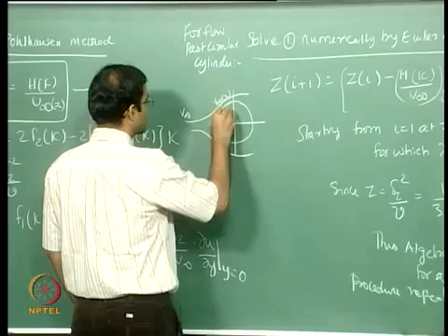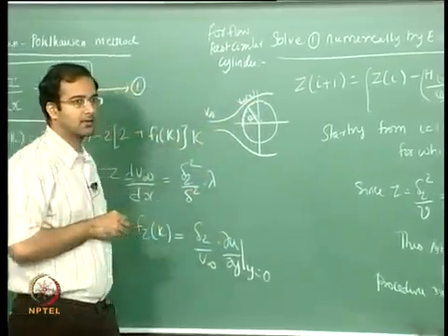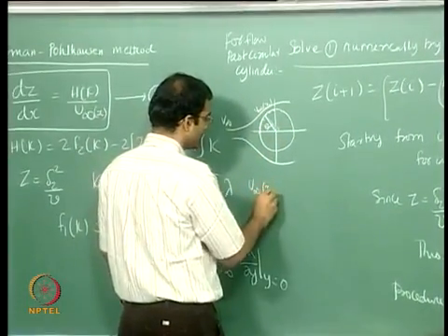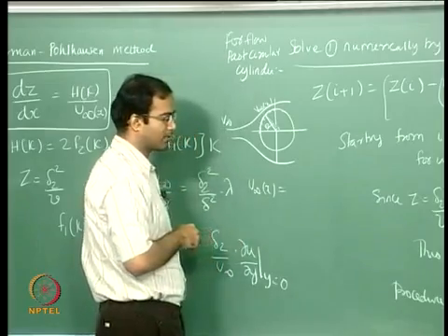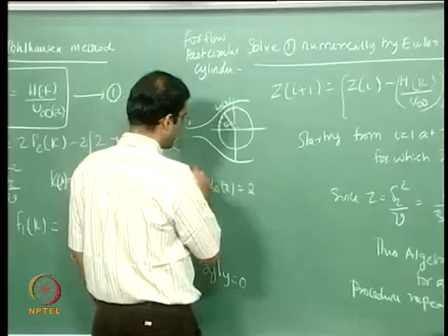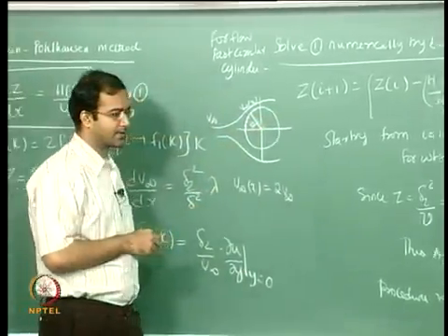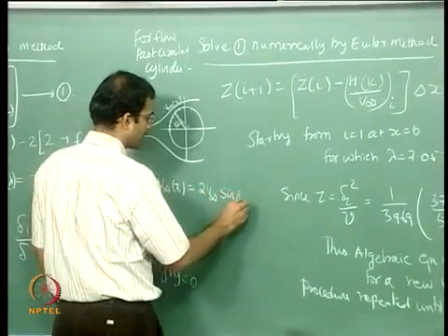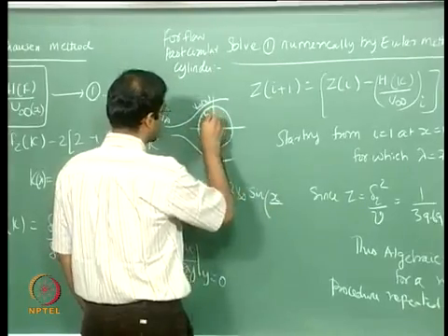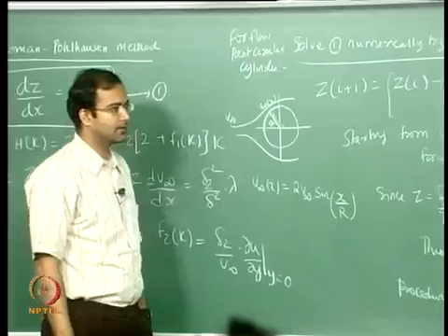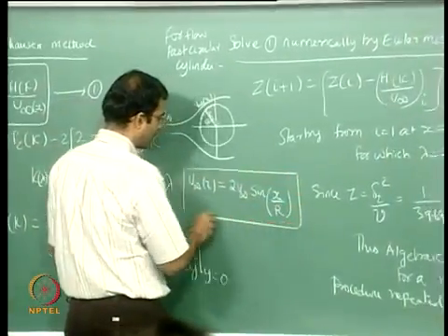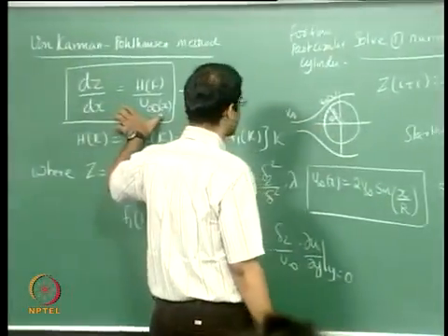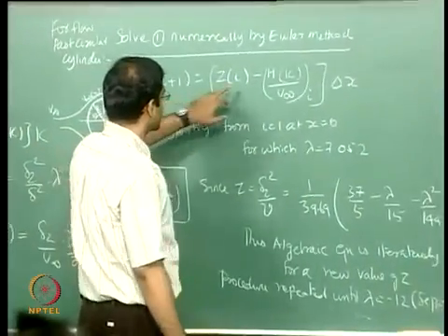We can discretize this particular ordinary differential equation for many points starting from the stagnation point. Suppose we want to apply this to the flow past a circular cylinder. For this we know the variation of the free stream velocity. Suppose the free stream approaching the cylinder is u infinity, v infinity; we can express the free stream velocity variation past the circular cylinder as u infinity sine x by r naught, or maybe I can use capital R to indicate the radius. This is the velocity profile obtained from the inviscid flow analysis, and now we directly integrate this ODE by the Euler method, starting from the stagnation point.